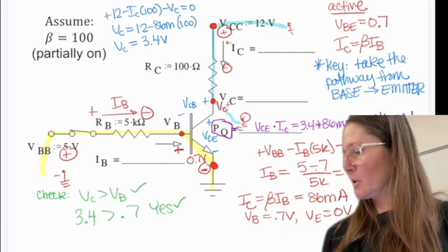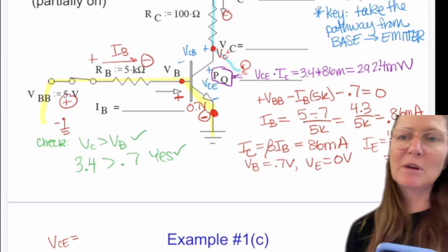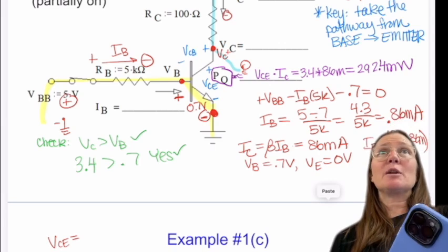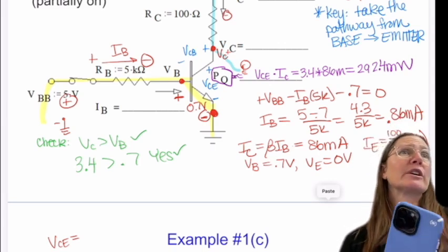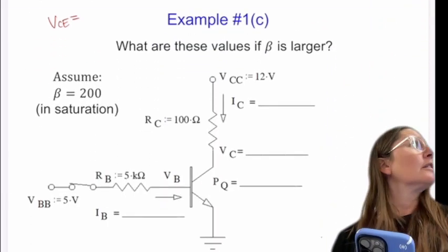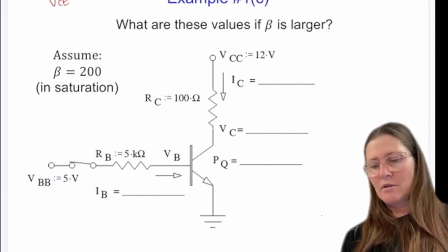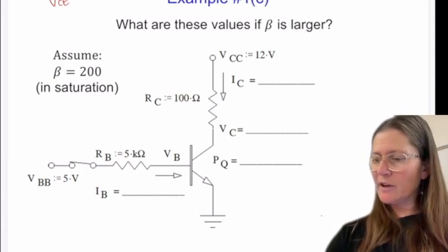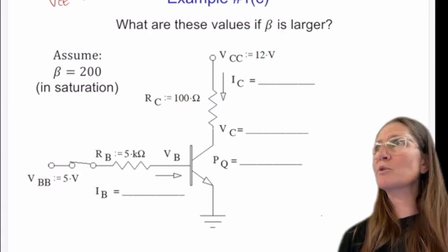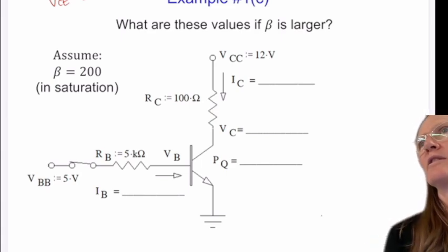All right. So yes, it's quite a bit of power being consumed there, but that still might not be a big deal. But you do need to check the capability of whatever device you're using. So you would look on a data sheet and it would have a max power rating on it. Okay, so moving now to saturation. So in this case, you're given that VCE is 0.2 volts, yes? When are we allowed to use the smaller power equation?